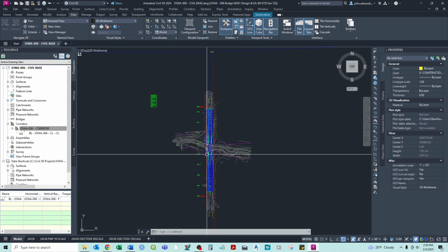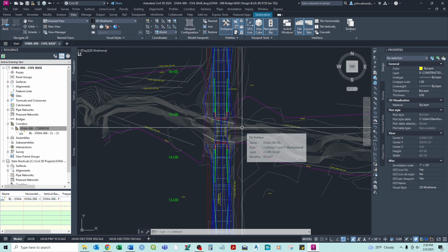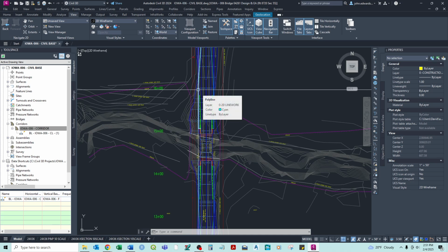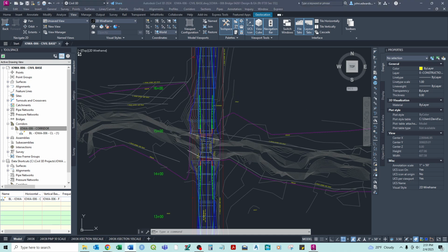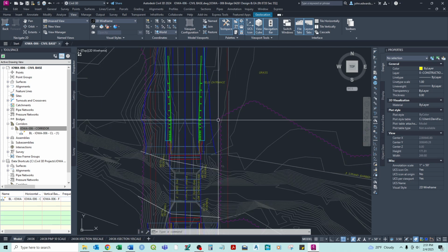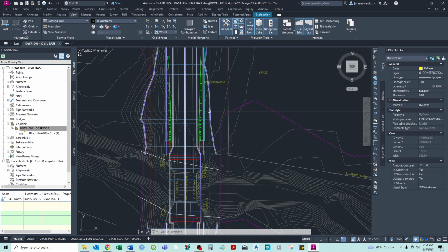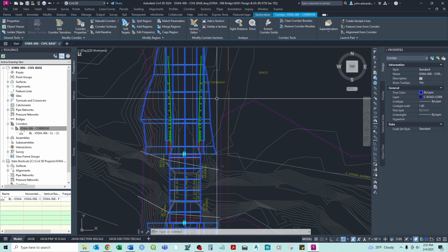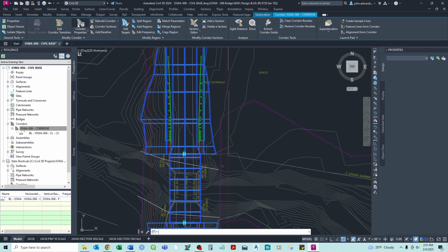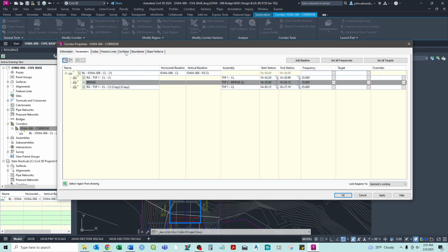So this is our initial base edit. Another thing that is really important to do once you have created your corridor, there's a lot more adjustments that will come, and we can work on those in just a minute. But the first thing I want to do is to create corridor surfaces. So we're going to go to corridor properties and come over to surfaces.